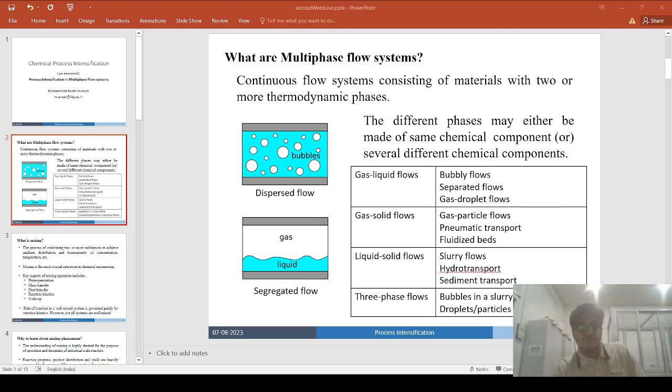But in the case of mass transfer, whenever there is an interface, you must also include another type of boundary condition, that is the dynamic equilibrium condition. One of the most commonly used idealized dynamic equilibrium conditions for interfacial mass transfer is Henry's law and Raoult's law. And if you involve multiple components also, then it becomes a much more difficult situation to analyze and study. That is why it is currently a very hot topic.